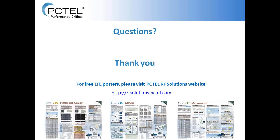Another question that we have, and probably I can answer this, is can you test uplink and downlink at the same time for spectrum clearing? Yes, sir. As I mentioned during my discussion, Seawave can actually do 2 independent scans at the same time. So you can either set it up as uplink and downlink for a particular band, or you can do two different scans on two downlinks or two uplinks at the same time.